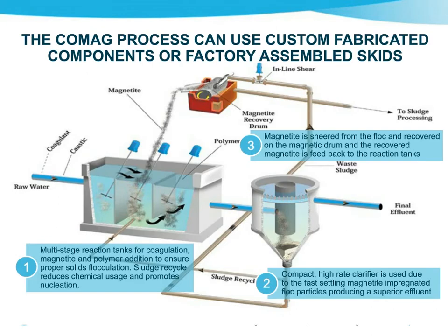A closer look at the multi-stage reaction tanks reveals a 3 to 10 minutes retention time in the coagulation tank. That's the first tank on the left side of the reaction system shown in the center of the slide. And there's a 3-minute retention time each in the ballast and polymer addition tanks. The flow is directed over a baffle from the coagulation tank to the ballast tank, and underflows from the ballast tank to the polymer tank to prevent short circuiting.